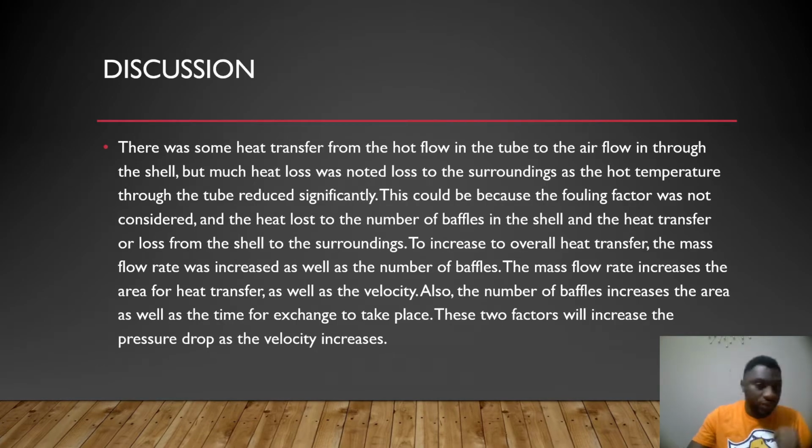For the discussion, most of the discussion is in my main project report, so I'll just say why I came up with this discussion. From the experiment, we notice that some heat was transferred from the hot flow in the tube to the air that flowed through the shell, but much heat was lost to the surroundings as the hot temperature through the tube reduced significantly.